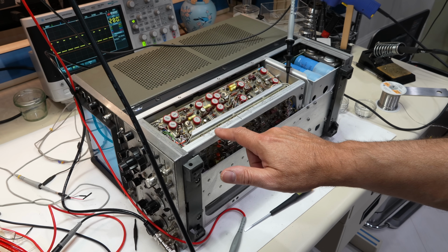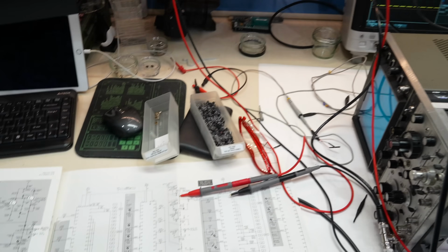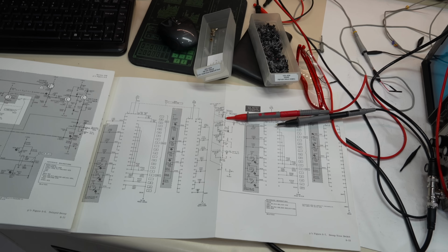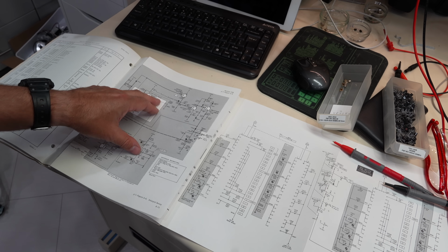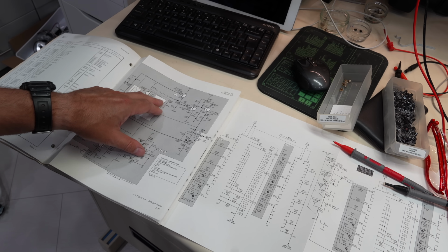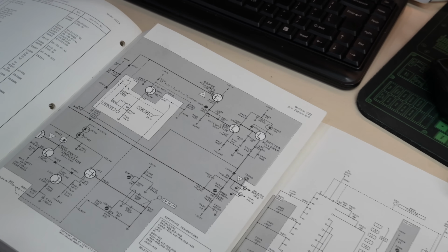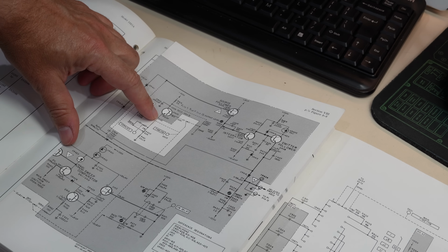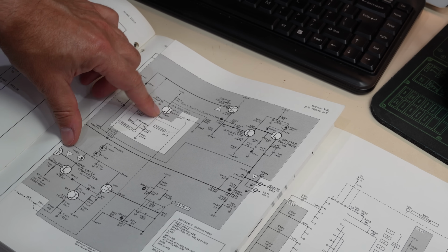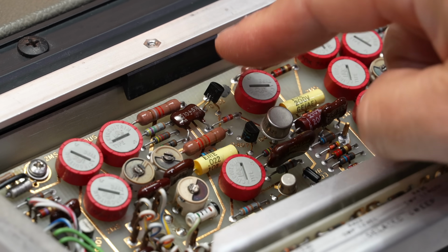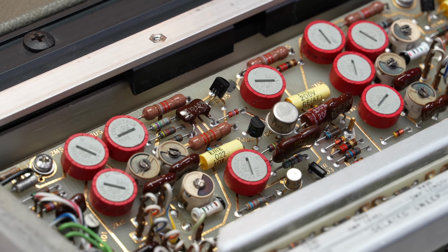However, on the delayed sweep, I couldn't calibrate it. Then I checked on the schematics, and sure enough, I checked that the voltage here was changing with every resistor, so that should have changed my sweep time. But when I went over here, that was not changing, so this transistor was not being a current source. This little guy over there, and in circuit it measures completely dead. I have no junctions whatsoever.